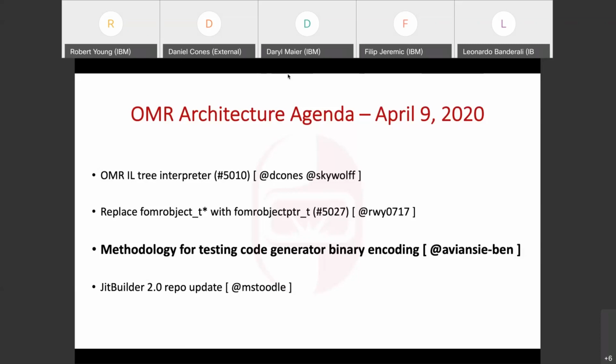So when you're actually generating the tests themselves, like the inputs to the tests, for a particular instruction, do you go through all possible registers that could be assigned to the target field? That would be far too much. So mostly what I do is, for registers, I would cycle through each register field, and everything except one register field would be register 0, and the one I'm testing would be register 31, so that the field would be fully filled with 1s rather than 0s.